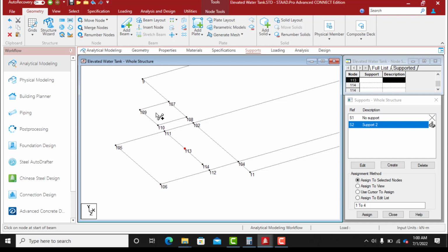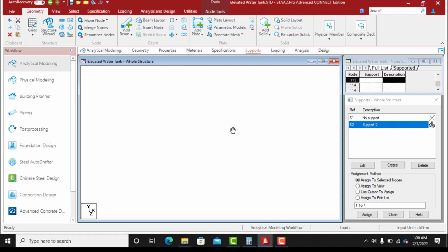We'll climb from the ladder. When they get to this point, we'll cross over to this landing. Yes, that's the standard. You don't put the access ladder straight from point A to the destination. There should be a resting point. So this is just one of the resting points and the landing. So from here, it will continue again to climb up. It is a standard that is generally accepted by the industry.